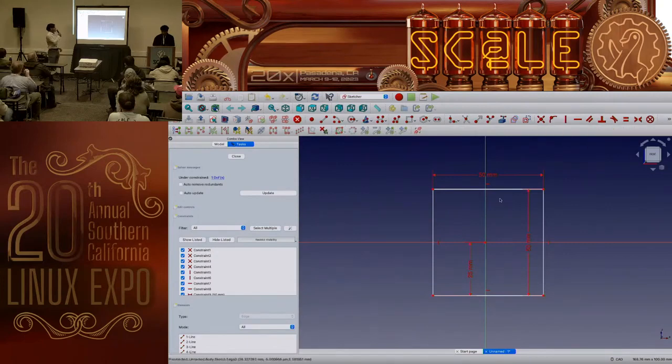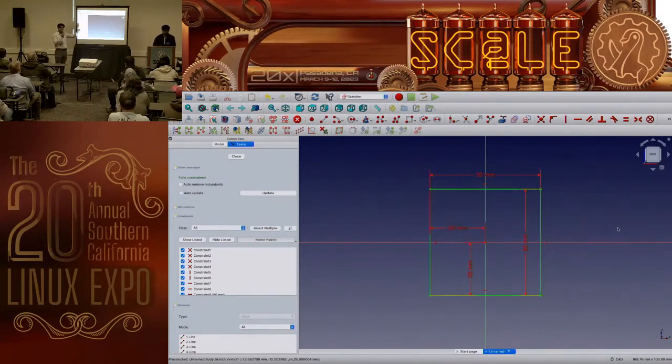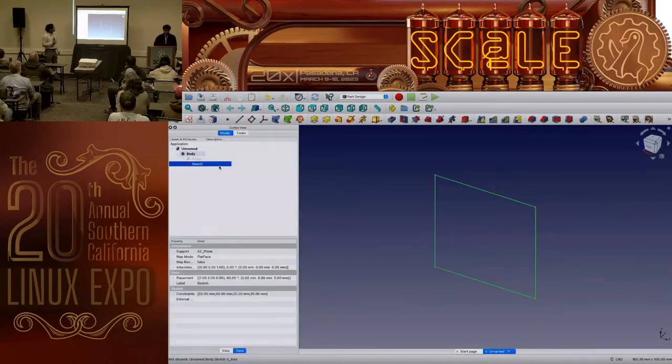You can also notice your degrees of freedom on this combo view, which basically tells you the constraints that are left for you to make until the sketch is fully constrained, and you can actually start to model it. So now that the sketch is green, that is when you notice that the sketch is fully constrained, which means that you can actually start to extrude or basically provide other dimensions. Okay, so now that we're done with this, it is fully constrained. We'll close that for now.